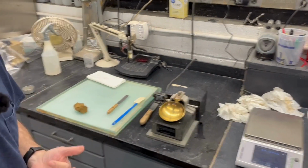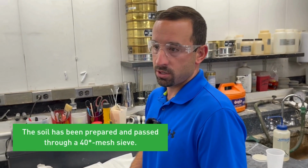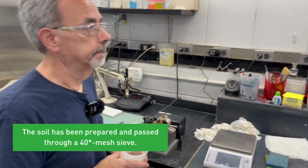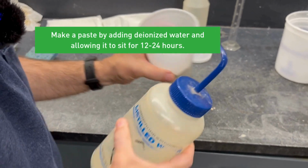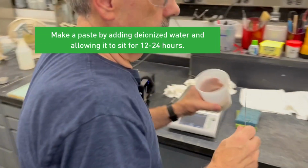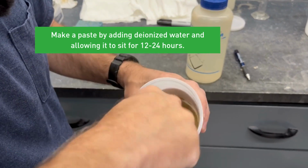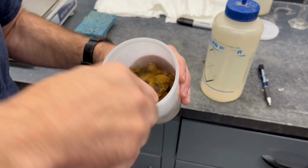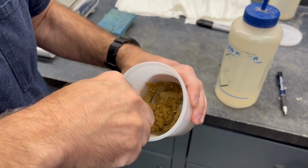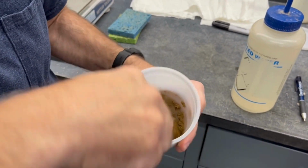Now we're going to mix up some soil, right? We're going to make a paste, so we have some dry soil that's prepped. We already passed it through a 4-mesh to make sure we have all the rocks out. You add water in stages, and you want to make not really a slurry, but a paste. You don't want to get it too wet. Play-Doh, right? Yeah, basically. So we're making Play-Doh today with Atterberg limit tests.